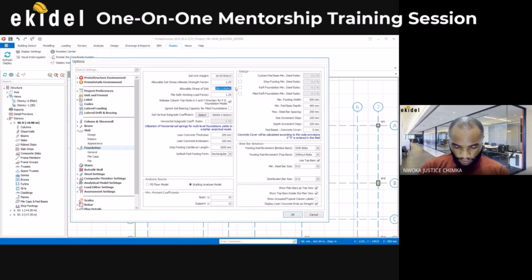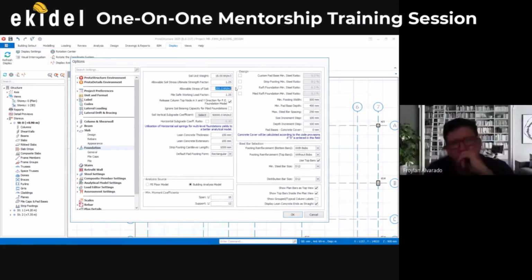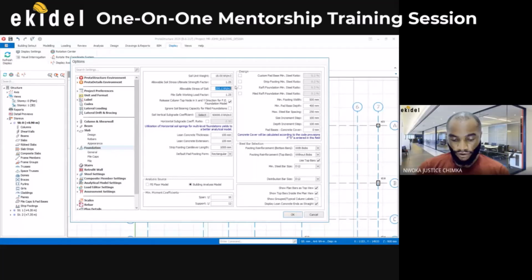Okay, from this place here, they said allowable soil is 200. They have ultimate 600, then allowable bearing capacity to be 200, which is 4,000 PSF. Then settlement, they say, is 0.65 centimeter.